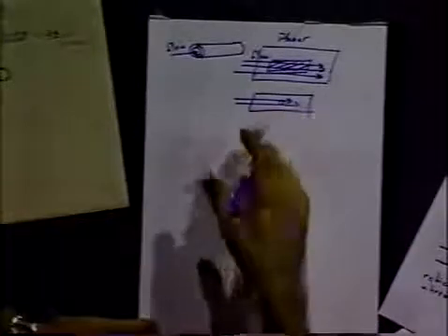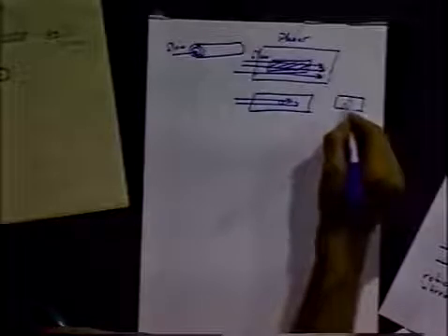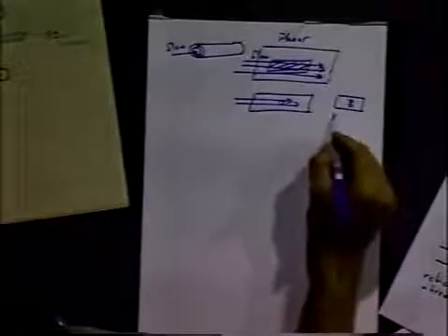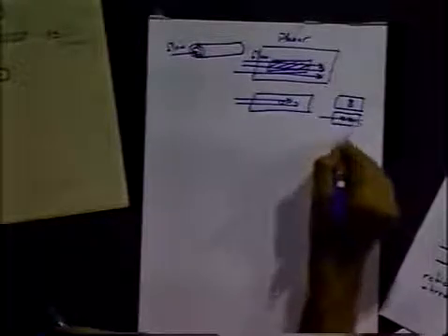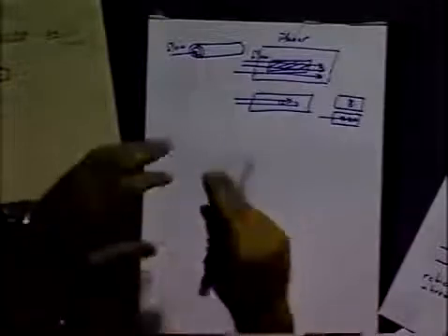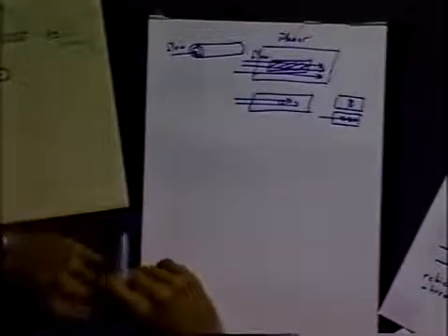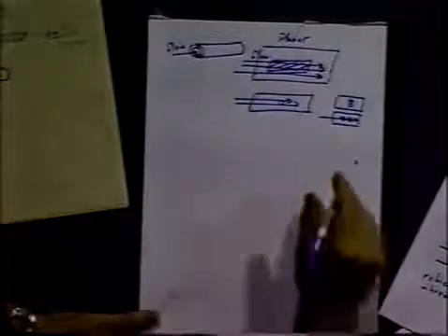And sometimes it's a single disc, sometimes it's a pair of discs. Either a pair can be opposed like so, or they can be serially arranged so that the flow goes over both of them. And by adjusting the potentials for the different electrodes, you can get some different types of detection methods, which we won't talk about right now.